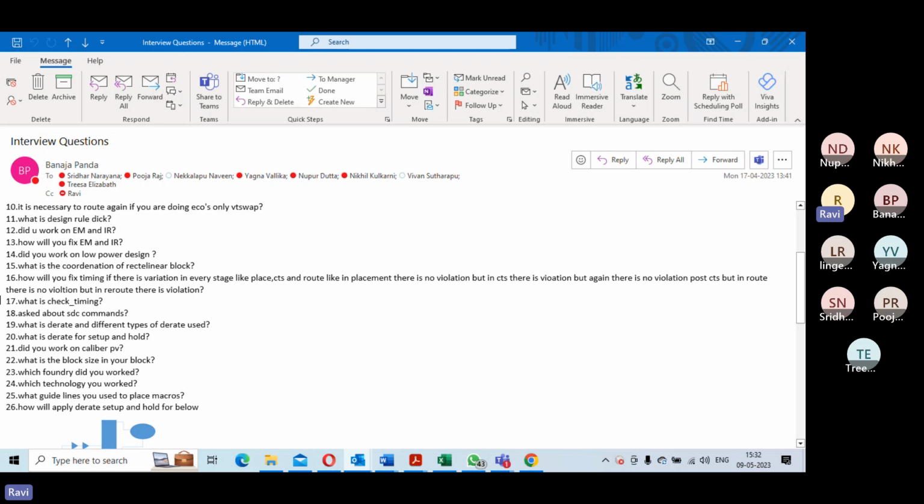By default, you can add level shifters from high voltage to low voltage and low voltage to high voltage. But high voltage to low voltage is in some cases not required, if the voltage levels are very minor and can take care of the voltage noise.